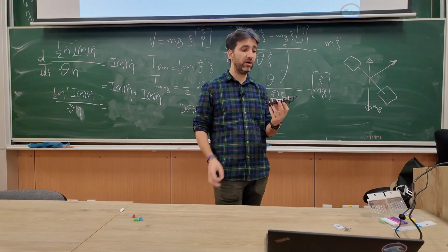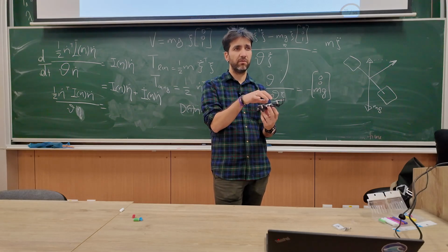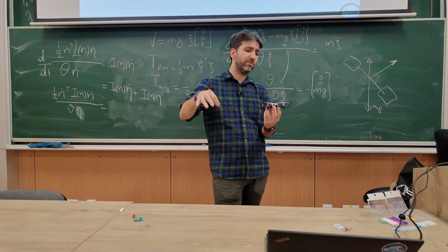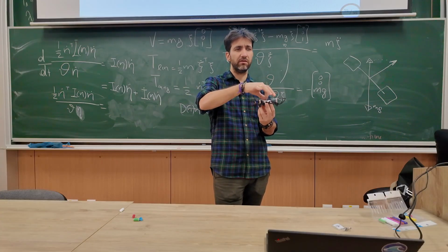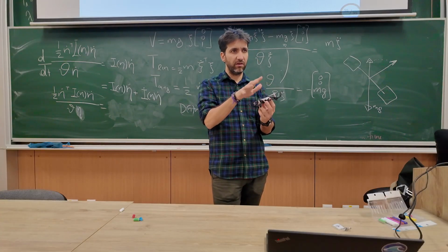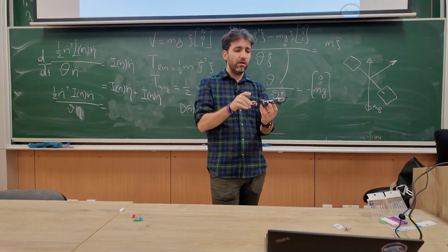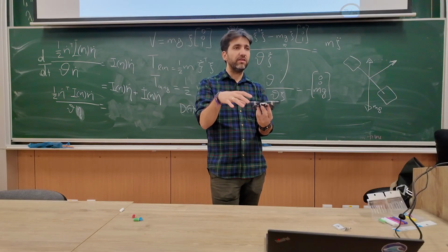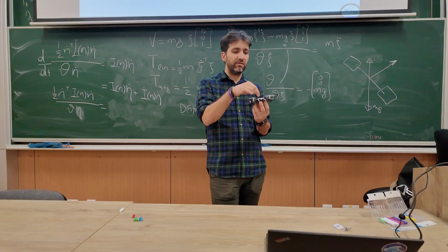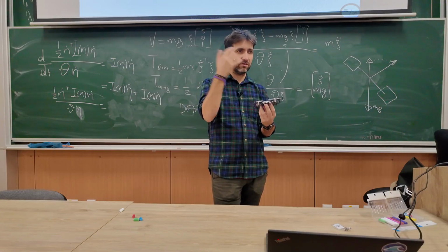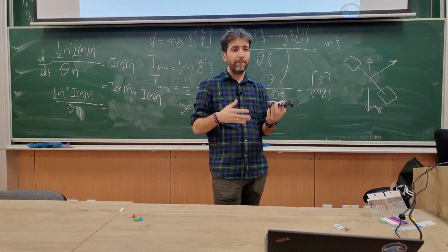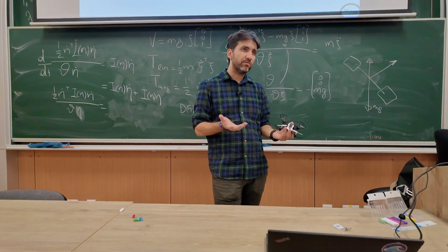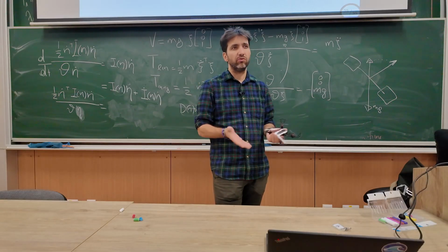Or you might not know where the center of mass is, because that's another parameter. It didn't appear in our calculations because we assumed the center of mass being in the center of the axis of rotation and everything being perfectly symmetric. But that's one thing, for instance, we didn't consider. What if the center of mass is not here and there? Then some calculation will change. But you need to have some assumption about the structure of the model so you can do system identification.